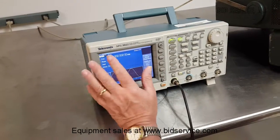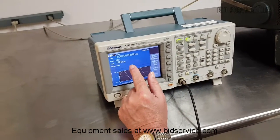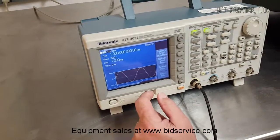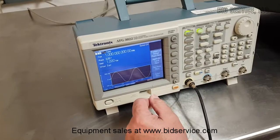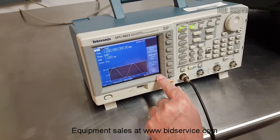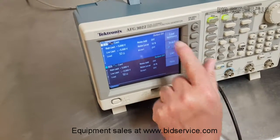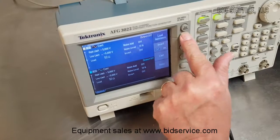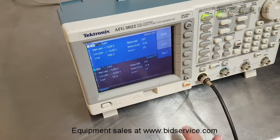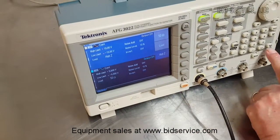Right now it's showing that we have a 1 megahertz frequency with an amplitude of 1 volt peak to peak. Due to the fact that I'm going directly into an oscilloscope, I've got to change the output, so it's good to show where this is anyway. So I'm going to go to the output menu, and I'm going to change the load impedance from load to high, and that way our output will match. And I'll hit enter over here,